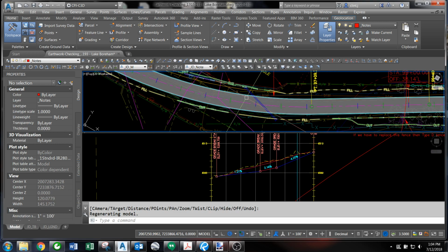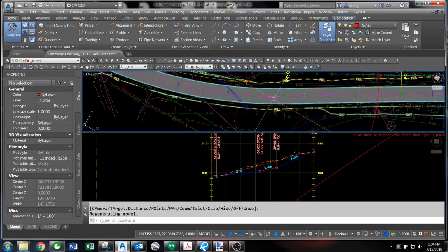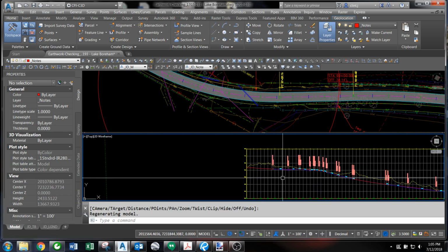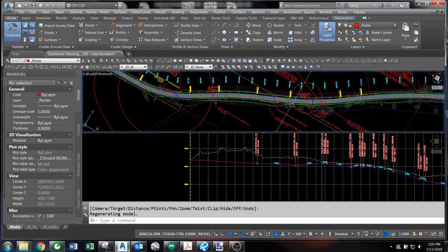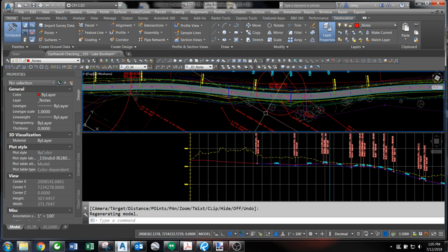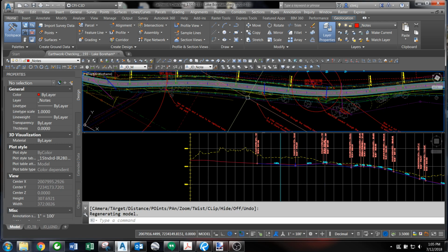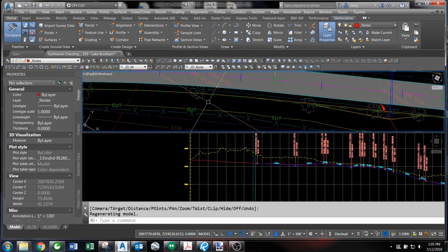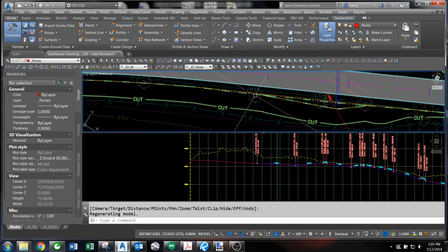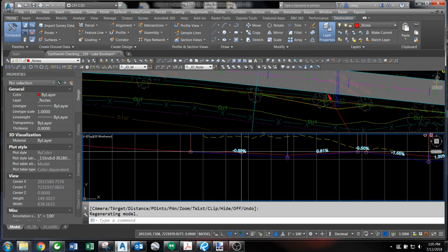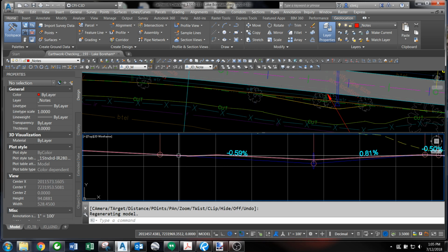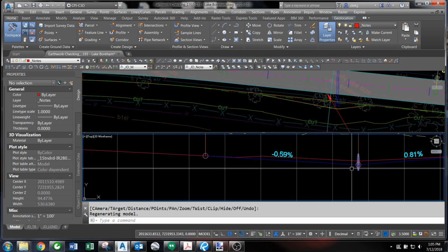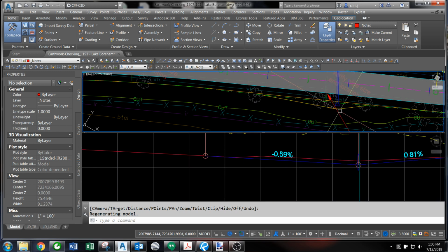That's how we're going to control the ditch, separate from whatever the center line's doing. Just because the center line's sloping a certain way doesn't necessarily mean the ditch is going to be that way. It's the same for this whole other half over here, I believe, the Clayburns over here. This one has a lot of that. We're just so shallow through here that we needed to start controlling the ditch in order to get good flow. Even then, we don't have great flow, but it's better than what it would have done without controlling it. It comes down and hits our culverts here, and we've got our inlet basins.